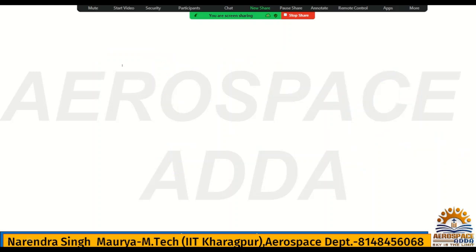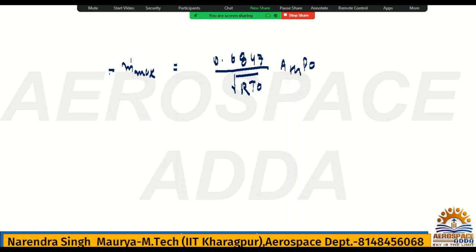We have the maximum mass flow rate formula: 0.6847 divided by root of R T naught, into throat area, into P naught. The maximum mass flow rate you just calculated is 19.04.